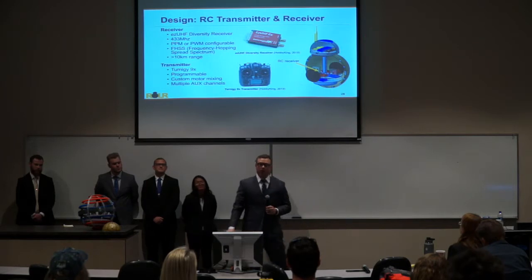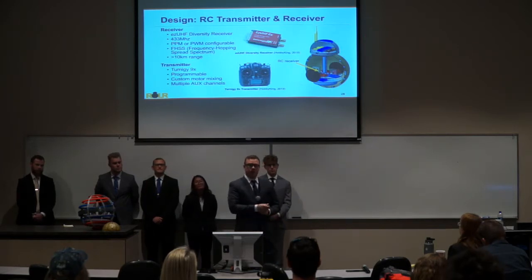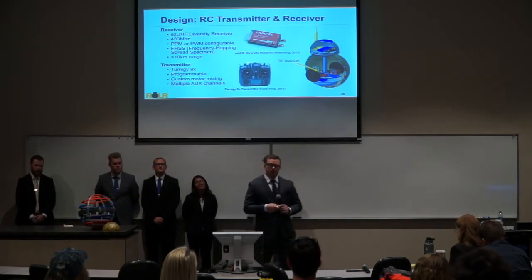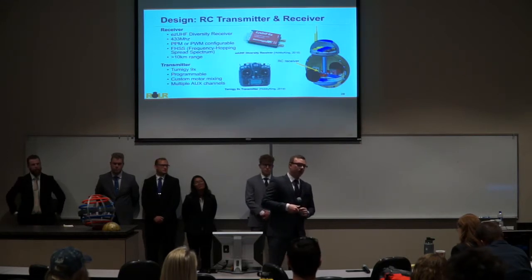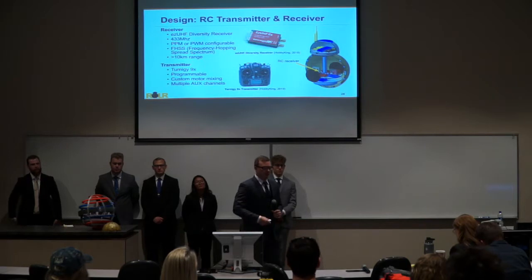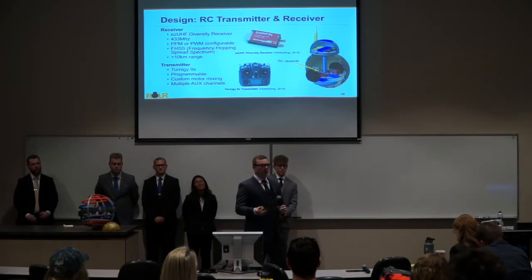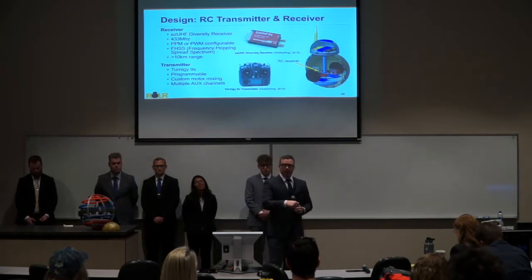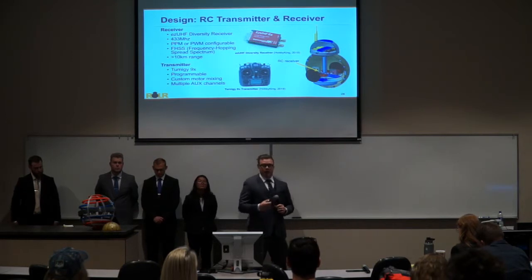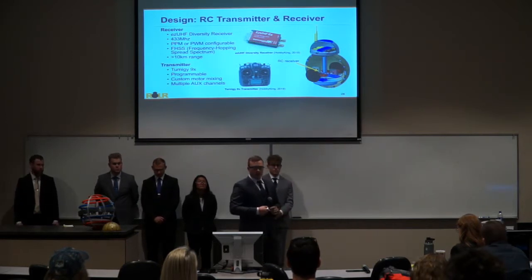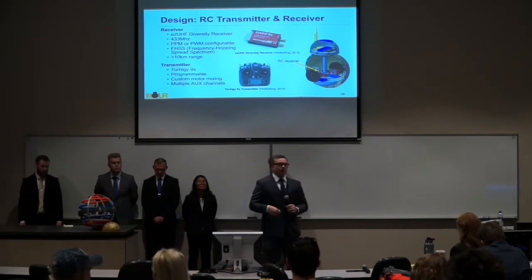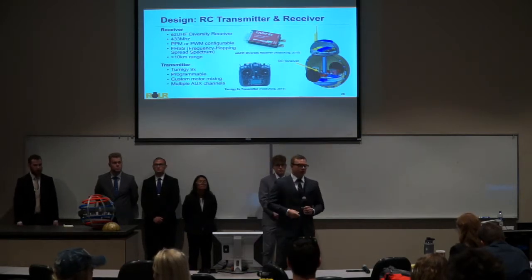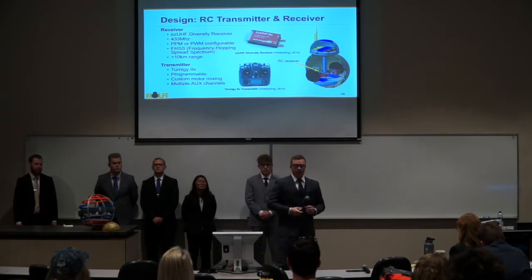To control ROLR remotely, we're going to be using an RC transmitter and receiver pair. These devices were selected primarily based on their frequency of operation. Since we have so many RF devices operating in such a close proximity, we need to make sure nothing's going to overlap. For that reason, we went with a 433 megahertz control system made by EZUHF and a programmable transmitter to go along with that, which will allow us to do some of that custom motor mixing to get the right translation and rotation out of ROLR.